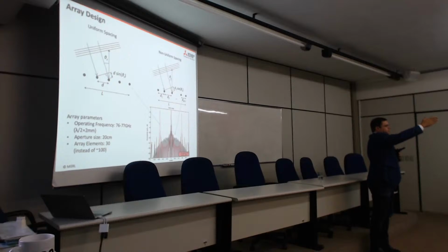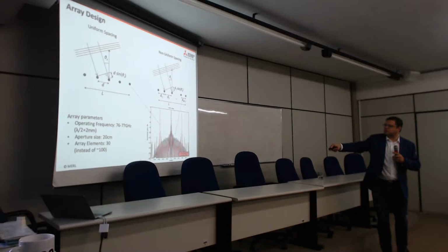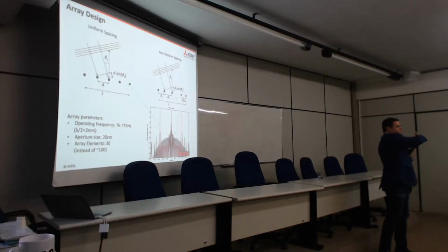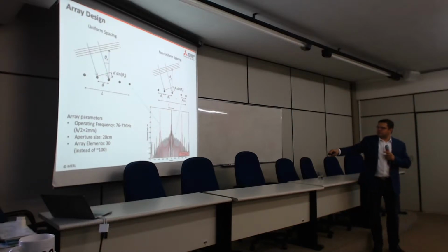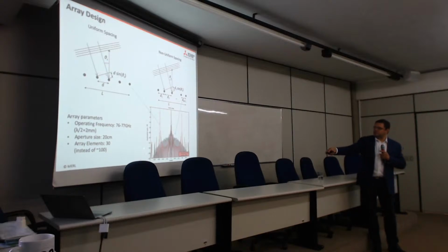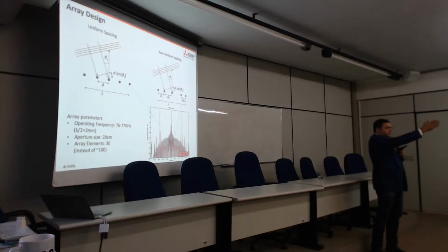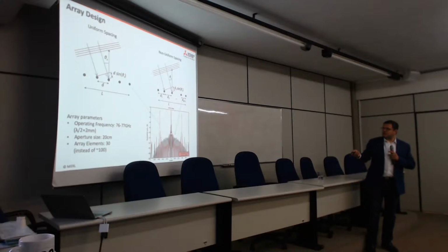So let's say there's something there and something there, something there. For every angle, and this axis is the cosine of the angle of the array from -1 to 1, it tells you how an element coming from there would appear, assuming I'm trying to look to the front. And if you have a uniform array, you'll see, these are the red curves. You'll see that certain angles, which is where the aliasing happens, are almost as intense as coming from the main lobe. So that means that if I'm looking there, but there's an object there, I will think it's there, or I won't know actually where it is. It might be there, it might be there, and so on. This is because I have a uniform array.